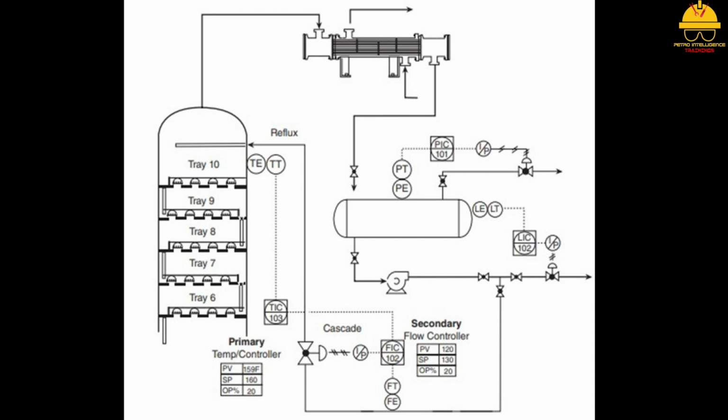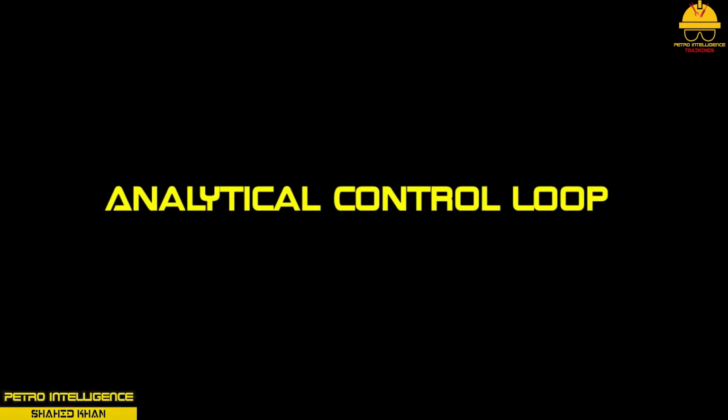point. During operation, the secondary controller operates with all 5 elements of the control system. The master controller has 1. Primary element, 2. Transmitter, and 3. Master controller electrically connected to the other control loop. This picture shows how a typical cascaded control loop looks.